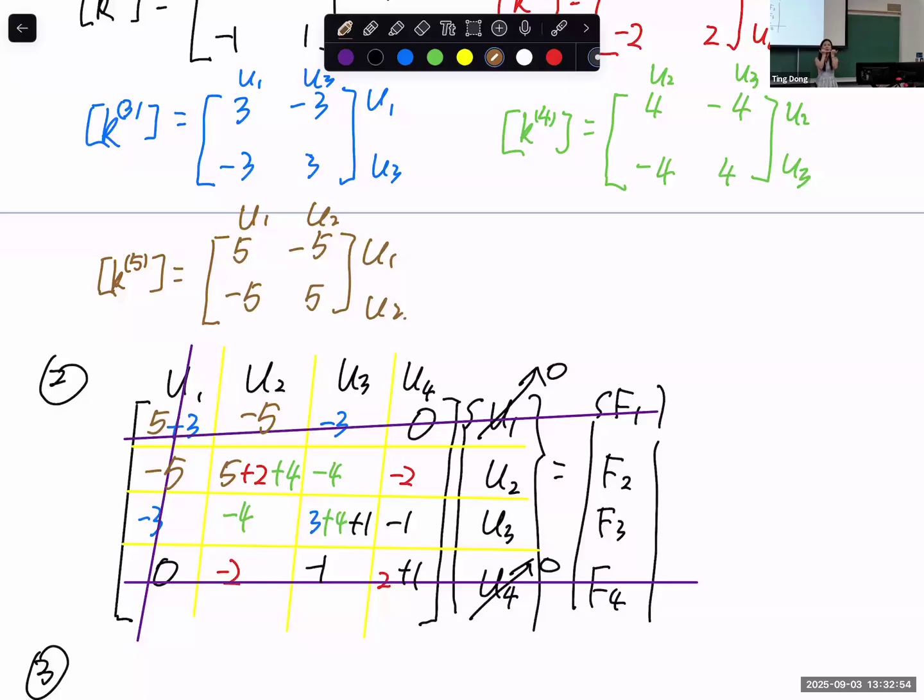We know that whenever I have tension, the normal stress should be positive, and the integration of the normal stress over the cross section should be positive. When I apply compression, the normal stress should always be negative, and the integration of normal stress over the cross section is always negative. So that is what the element force P here means, and it is the same idea as the internal force in mechanics of materials. Same thing.